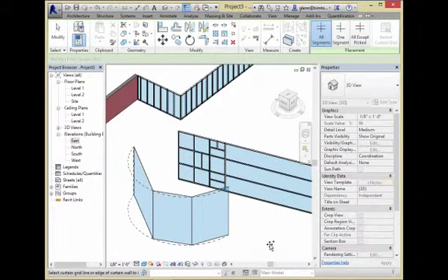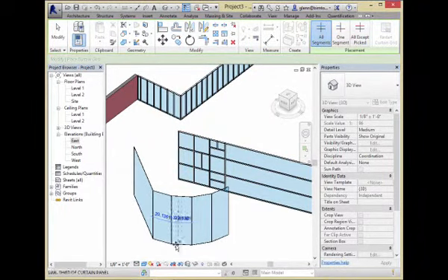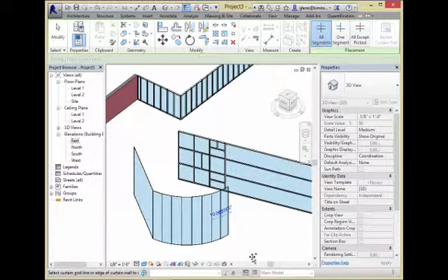Where are you, Mr. Grids? I'm going to put it over there. It's easier to see. I'm a little oblique to it right now. But the finer I break that up, the better it's going to do at rounding the curve. Now the cool thing is, if you're using a pattern-based curtain wall and the panels are small enough, it'll take care of all that breaking for you. It just follows the curve automatically. But watch out for that. If you're doing a custom one, watch out for your curved surfaces because you may have to break them up to get them there.